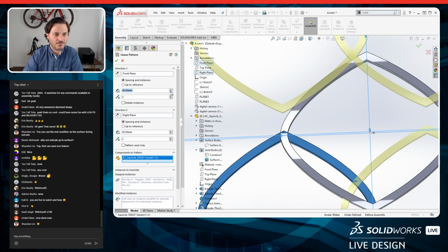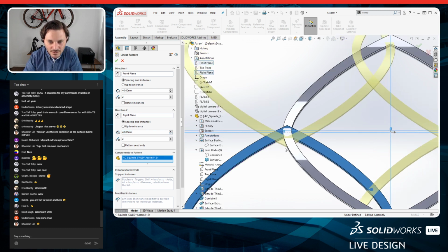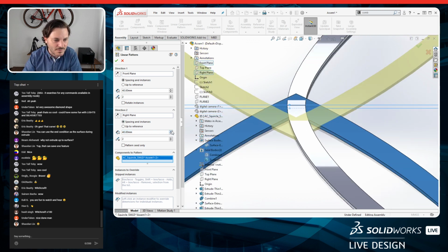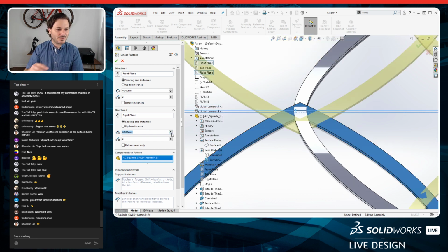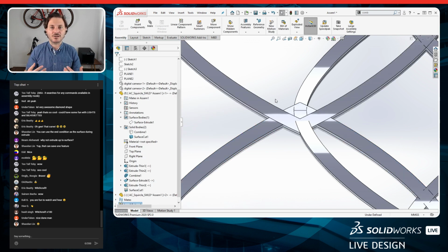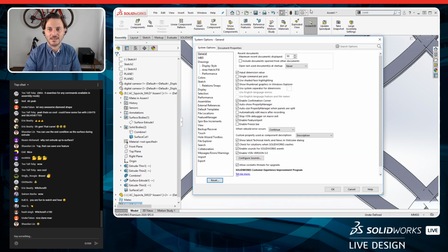So if I move this around, I can get close. Well, it looks like it's stuck at 10 millimeters. Boy, that's some really coarse adjustment, isn't it? Maybe it's more like 42 and a half. I could start punching in different numbers to try to get that value perfect. Or what I can do is change what we call our spin box increments, because I just want to lightly tap this thing into place.